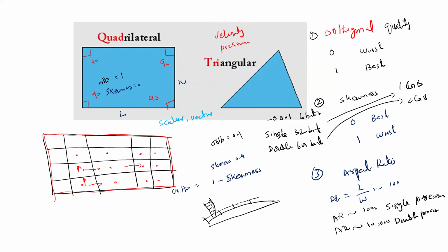These quantities are solved, for example, on the cell centers, and the fluxes, like velocity and others, are solved on the faces. When we solve for these vector quantities on the faces, the two cells are joined in this way.